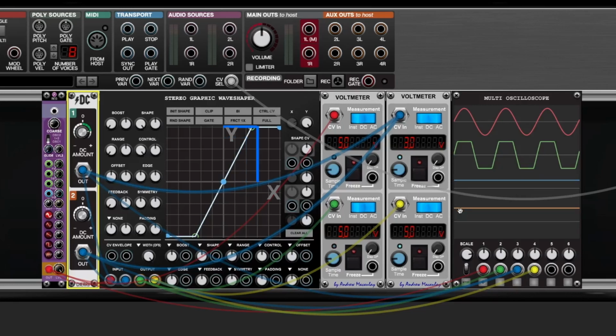And this applies to every signal you put through the waveshaper. We can conclude, waveshaping reshapes the signal based on its amplitude and a specified shape by mapping the incoming signal level to a new outgoing level. Now, how is this of any use? Well, oversimplified. That's how every type of distortion works. Distortion is a nonlinear process, so if we move away from the default straight line, we effectively apply distortion to the signal. In fact, we will explore many types of distortion that you can facilitate with this waveshaper later on in this video. First of all though, we need to familiarize ourselves with the interface.